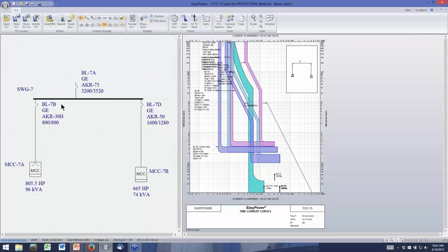Now the NEC requires ground fault protection only on the main device above 1,000 amps or whatever it is. That's more just a fire protection issue, right? The NEC doesn't, in general, require that things coordinate except for emergency power these days.